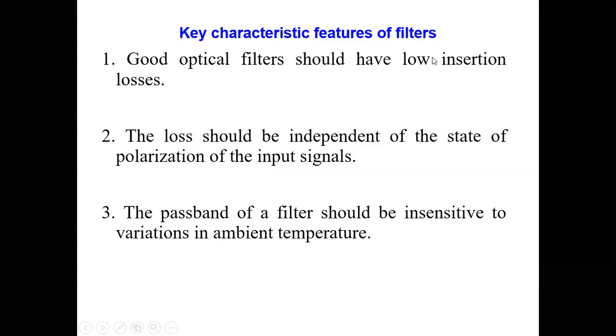Okay, so see what points are there in my slides. A good optical filter should have low insertion loss. The filter itself should add less loss, low insertion loss. The loss should be independent of the state of polarization. See, whatever points you said were the general things.